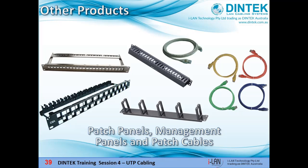One thing you don't want in a fire is a cable that acts like a wick and transfers the fire into other areas, or takes people out with poisonous fumes as it burns. PVC is slightly cheaper and more flexible, but if it's going into a populated building or an enclosed area where people can't always evacuate quickly, it's better to run with LSZH cable. Building codes in many areas might also require it.